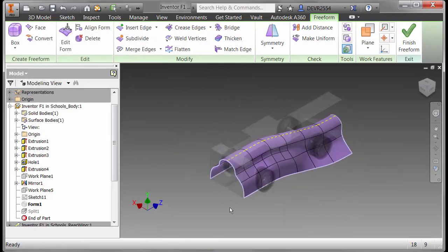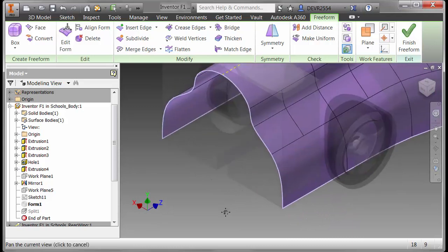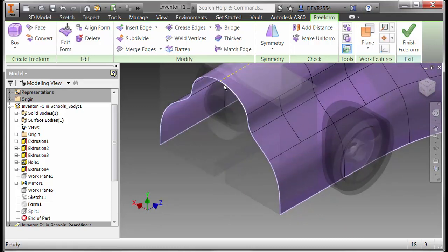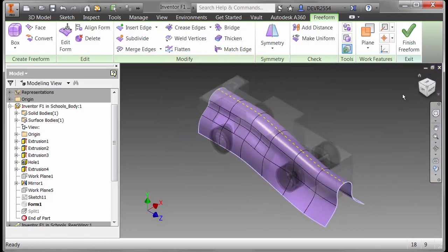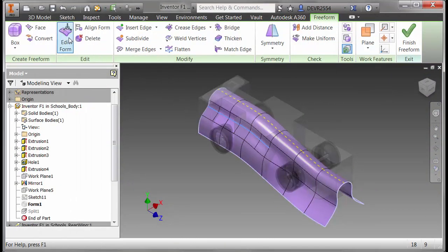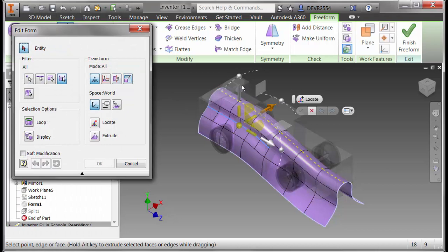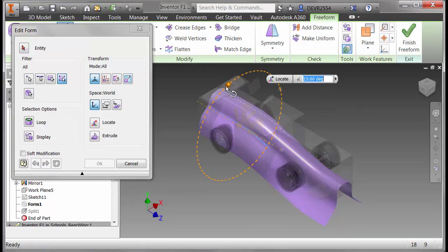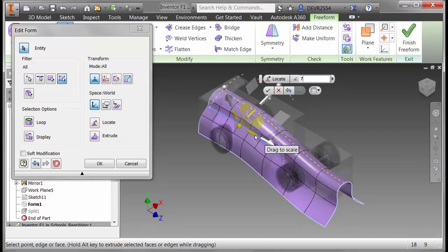Now before I go on, we wanted to focus on design and the rules of the competition. One of the rules is a minimum of 3.5 millimeters between that cartridge and the outside surface. So keep that in mind. You can make some changes here, but they may not meet with the rules. I've selected that edge again. And I want to just change that by dragging that around counterclockwise. And I know I want a value of 70 degrees.